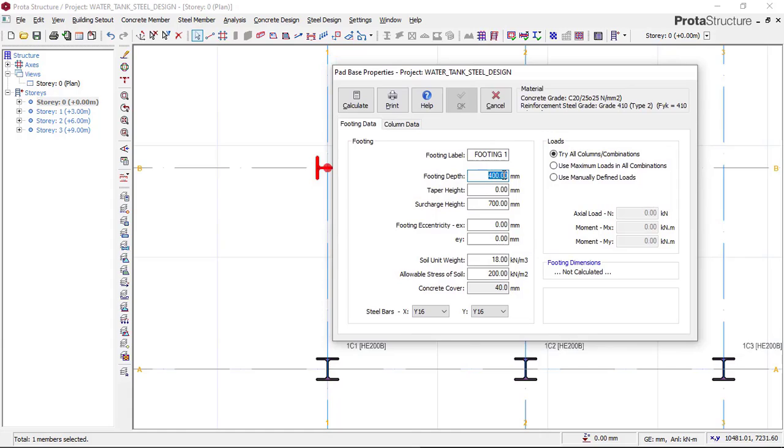So we go now and choose our footing depth. I will take my footing depth to be 350. Let's see if that will pass. If it doesn't pass, we'll come and increase it. Then the next thing, I'll leave here as default. You can check my previous videos on foundation design, where I really explained all these parameters, whether you have to put them or not. So for now, you only put your footing depth and then you go over to your allowable bearing capacity.